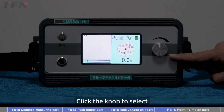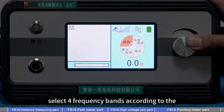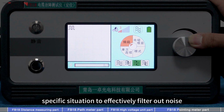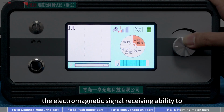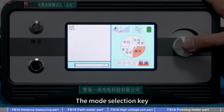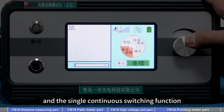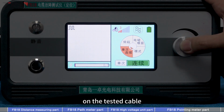Click the knob to select. In the frequency band selection, select one of the 4 frequency bands according to the specific situation to effectively filter out noise. The electromagnetic gain setting can control the electromagnetic signal receiving ability to more clearly display the electromagnetic signal changes. The mode selection key can return to the step voltage mode, and the signal continuous switching function can perform single or continuous signal monitoring on the tested cable.